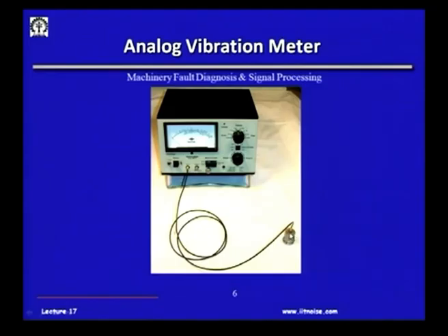This is shielded from moisture, humidity, rain, etc. And then this cable, because as soon as the charge is produced, we will go to the details of the vibration transducers regarding the mounting, etc. in the subsequent classes. But suffice it to say a charge is produced, and this charge goes into an amplifier wherein the charge is converted to voltage.